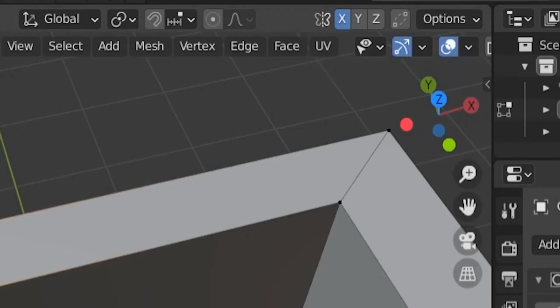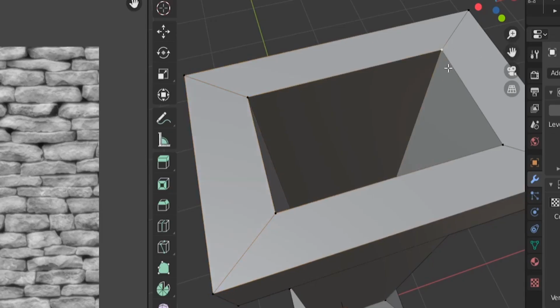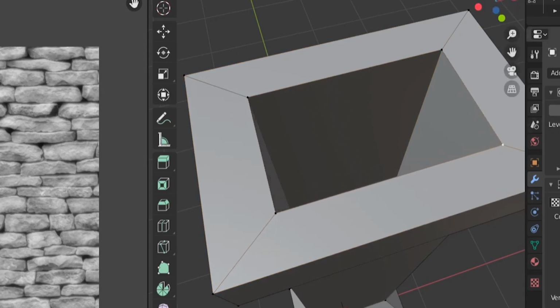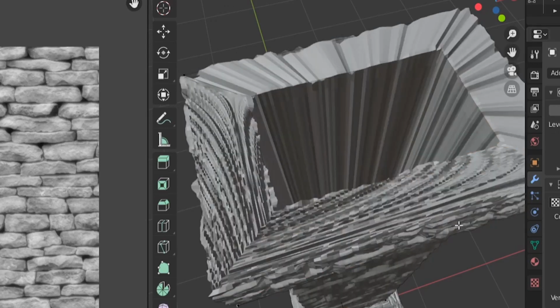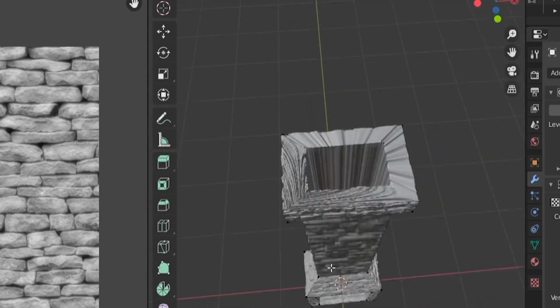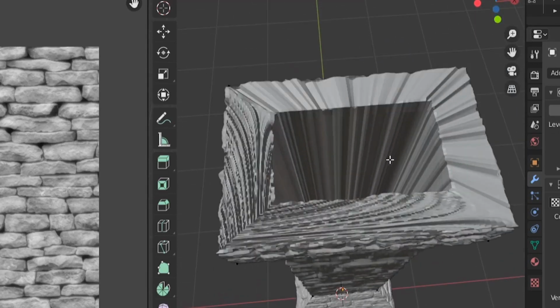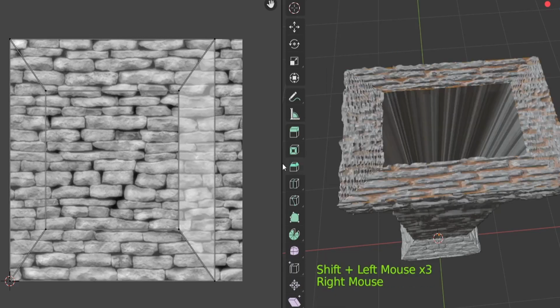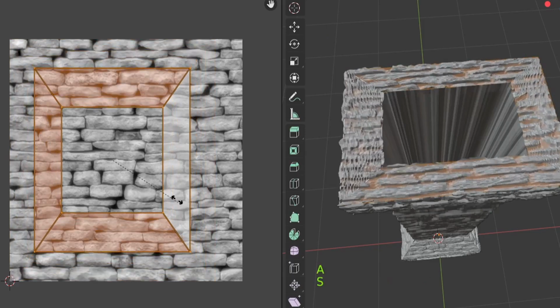If we try to mirror now, will it work? Select G. Oh yeah, it works. Nice. The mirroring works, but we will disable it for now. Let's enable subdivision and then enable displacement. Oh, so now we fixed that issue we had. So next time when you join 2 vertices, use J. So we select these 4 faces and then we do unwrap and then let's do A and then resize.